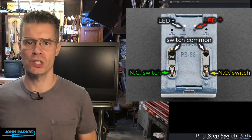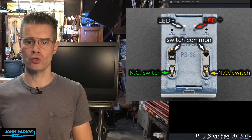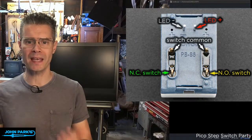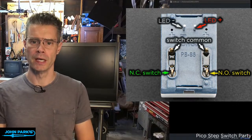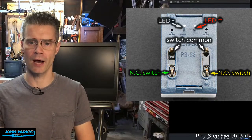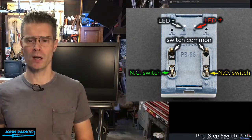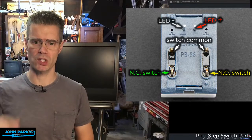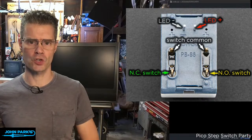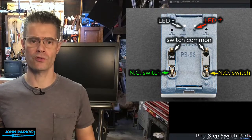So if you're using digital pins on a typical microcontroller at 3 volts, then you want to put a 1K ohm resistor in line with either side of that, and then you can feed it a digital out. You could also PWM it if you wanted to adjust the brightness, but I'm using it just in a straight 3 volt out, then going through the 1K.